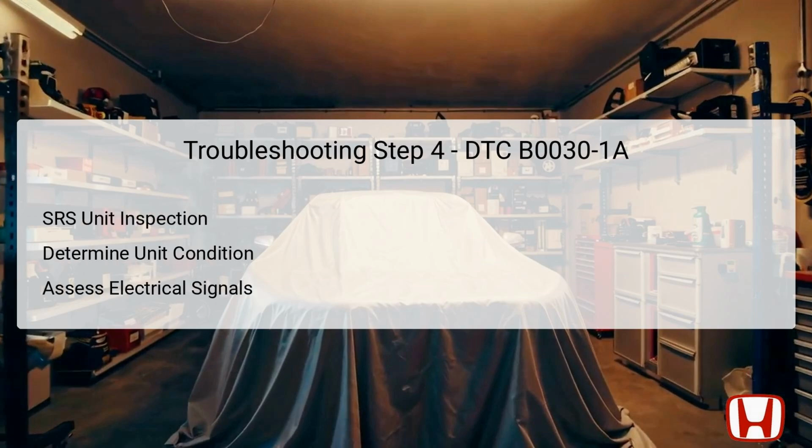The final troubleshooting step assesses the SRS unit itself. If prior inspections of the left rear side airbag and the associated wiring have indicated normal operation, this suggests that the SRS unit itself may be at fault. The SRS unit is essential for processing input from various sensors to determine when an airbag should deploy. If it isn't functioning correctly, it may misinterpret the conditions and store a false DTC.